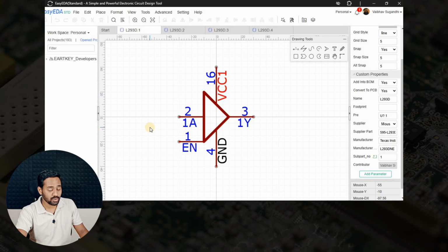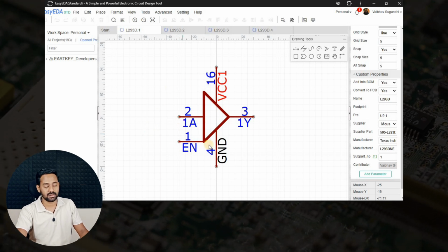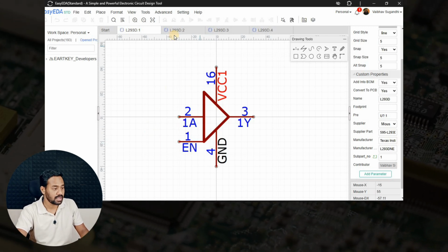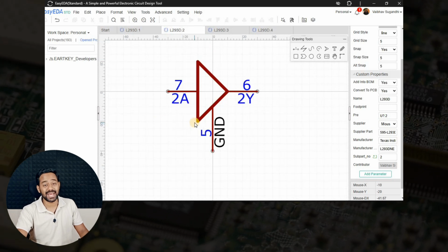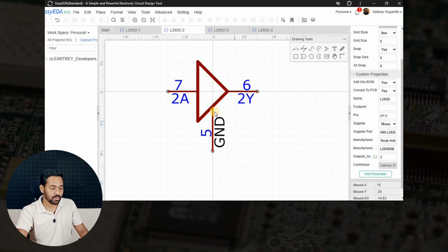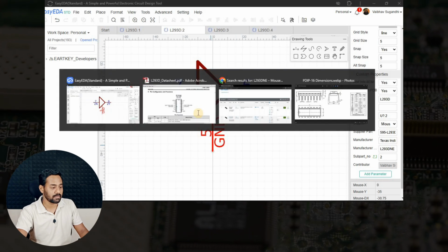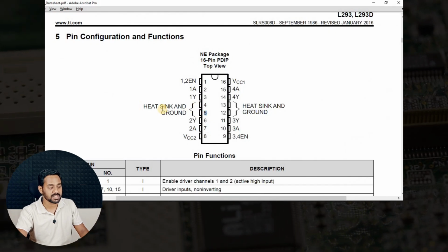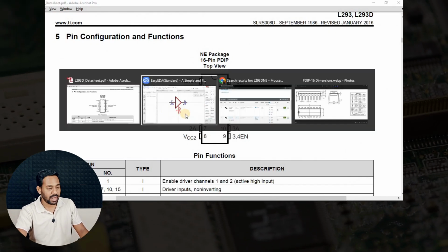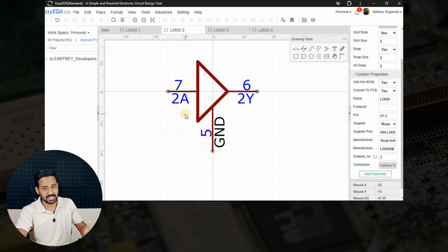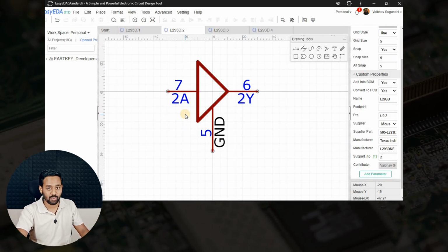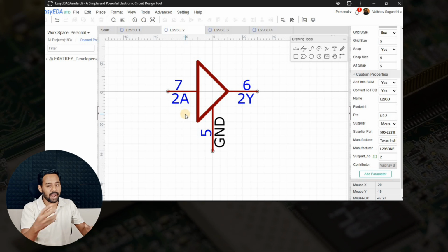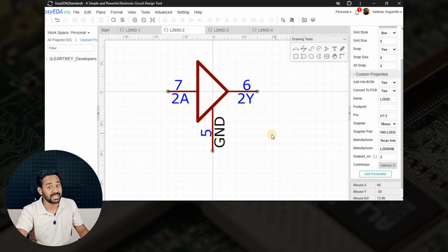Enable 1 is given to a particular pin in the first subpart. In the second subpart, we do not have enable 1. And also we have given a ground in this. Why? Because we have 2 ground pins for one particular side. And to manage the entire 16 pins in the schematic symbol library combination, we have to give an extra ground in the second subpart.